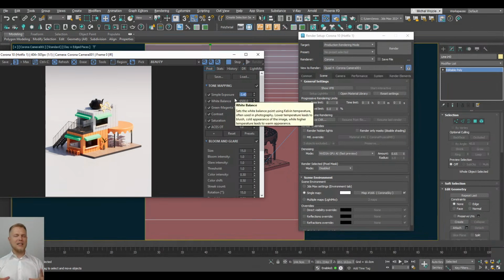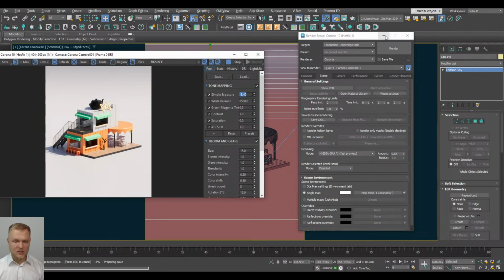Okay, you might have noticed that all of my image is a little bit orange-ish and we're not especially loving that. So how about we change this a little bit? First of all, I'm going to select my sun in this scene and change its input from realistic to direct input. That's going to allow me to directly control what kind of color we're going to achieve using that sun.